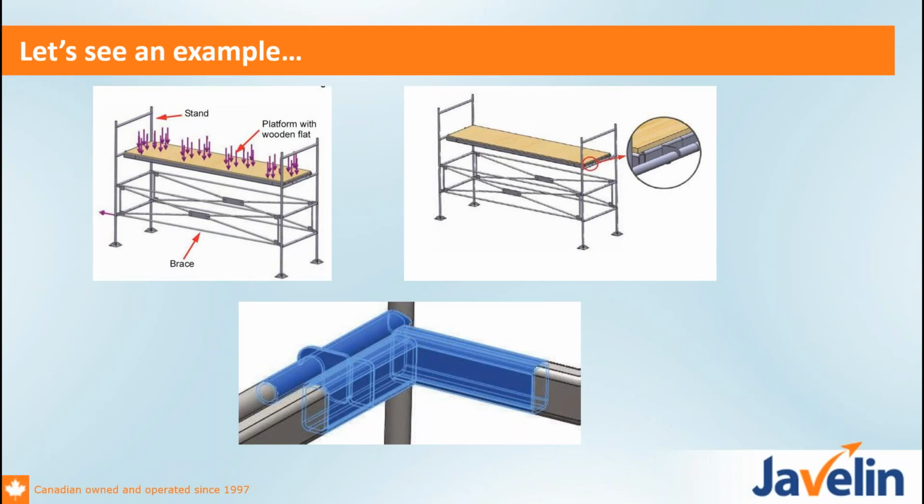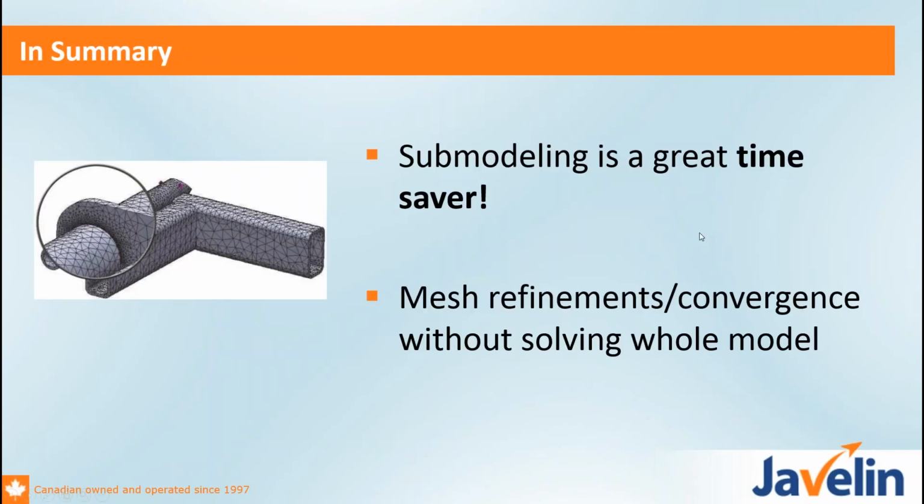Now, we'll start by running that as a master model, very, very coarse mesh, or sorry, a parent model. Then we'll do a submodel just on one of the hangers, and with that, we're going to isolate some of the components. And one useful thing you'll see here, guys, these beams that have been split in the corners, the ones that are highlighted in blue, those have been created by splitting a beam into two beams. You can do that just by creating two end-to-end sketch lines with beam elements, or using the split command to split bodies that way. So it can be useful to split your bodies if you want to look at small areas of those bodies. Now, I'm going to pop into SOLIDWORKS and show this to you guys live.